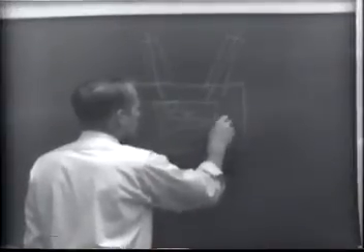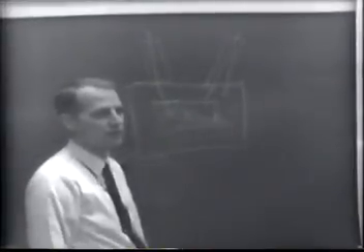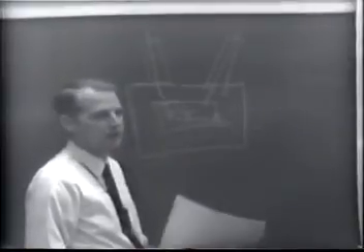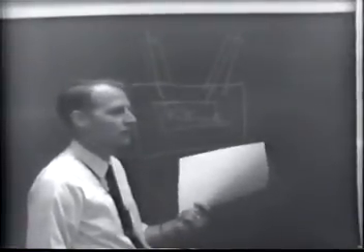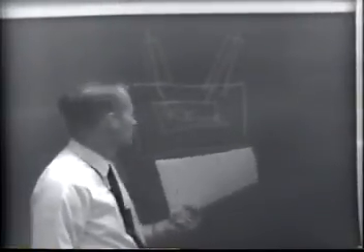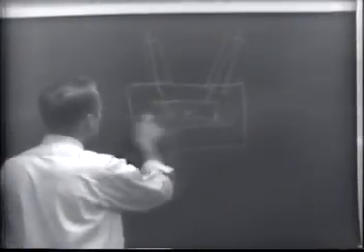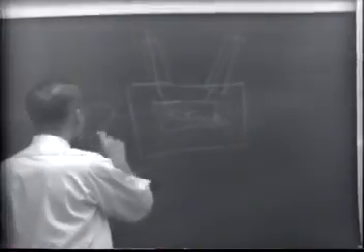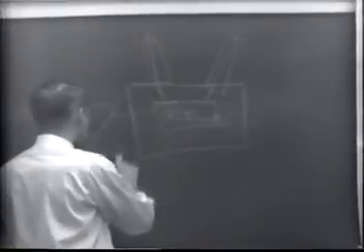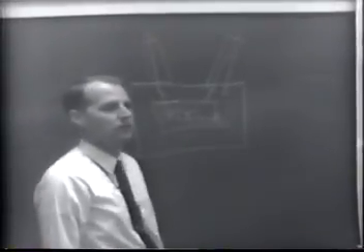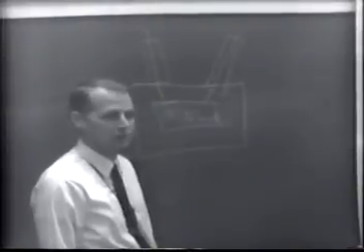This is the device that's going to interrupt the arc. It's going to increase the dielectric strength between the contacts so that this piece of equipment can function as a circuit breaker. And then finally, we have to have some kind of an operating mechanism that we can control. We can operate it remotely.